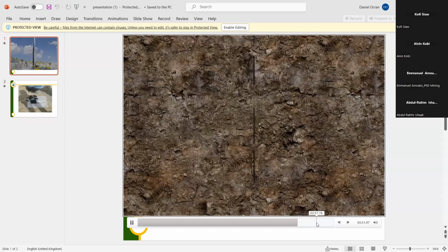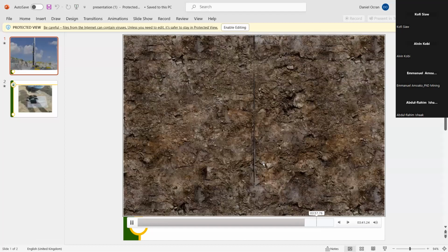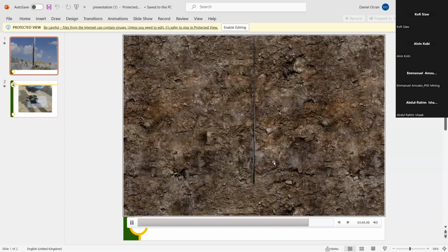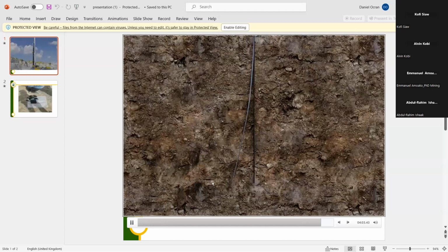So we have the actual path. So this is what happens if you have some discontinuity in the formation. You can see this is typically what actually happens underground, where you usually have those hole deviations. In the initial images that I showed, you can see that we have these pre-splits, which are usually not following the actual hole design. So you can see the hole deviation that is taking place over here.